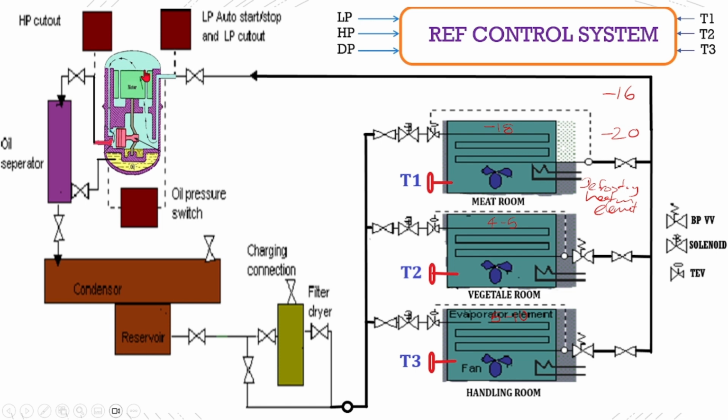Why is it so? It is a kind of superheating theory, and it serves two purposes: cooling down the motor, because the electrical motor produces heat, so by sending this refrigerant it will cool down the motor, and the heat will be taken by the gas, so the gas will get superheated.